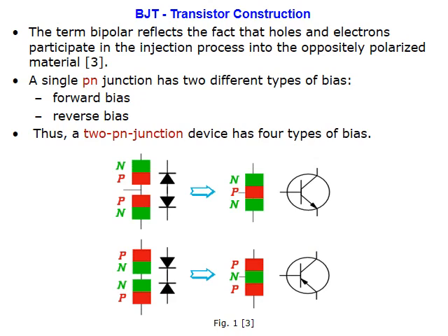Now what is the symbol for the transistor? As you can see here, this is the base, and this is the line going outside. This is collector, this is base, this is emitter. This is how the symbol looks. And frankly speaking, this transistor is actually represented by two diodes in opposite directions, a diode in this direction, a diode in this direction. This is base, collector, emitter. NPN, and the opposite direction for PNP, with the diodes face to face.